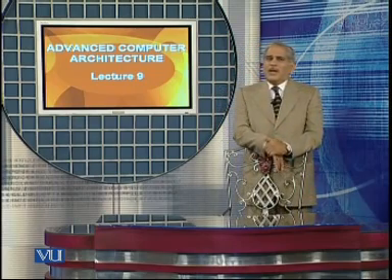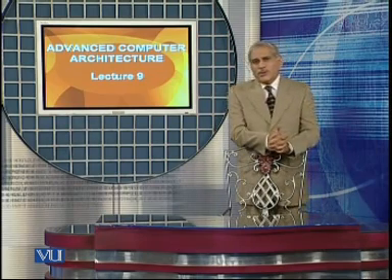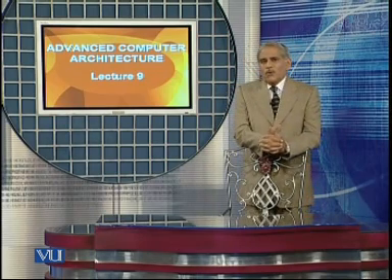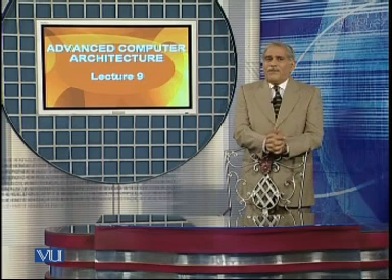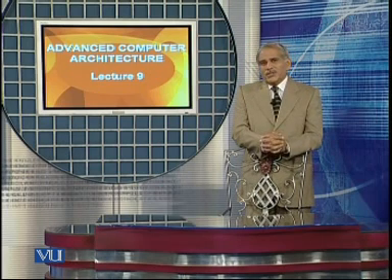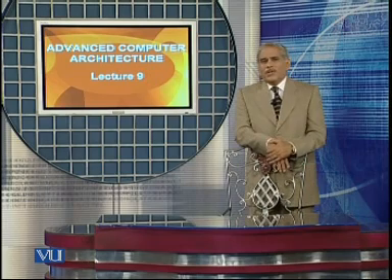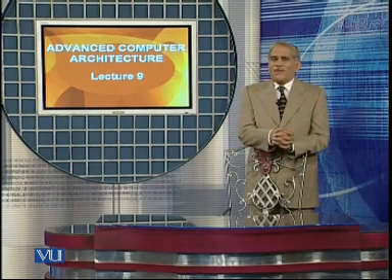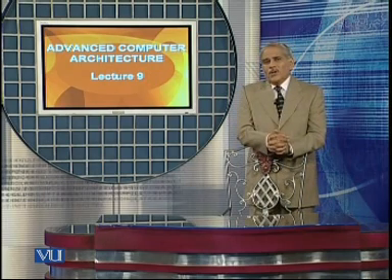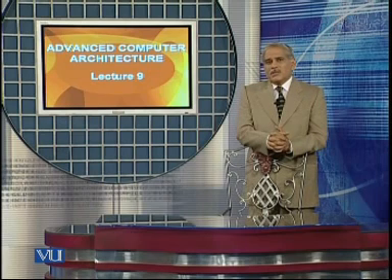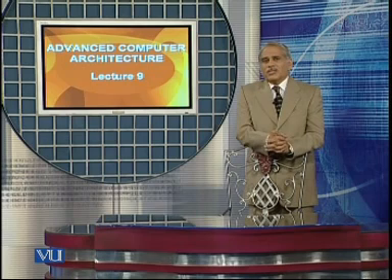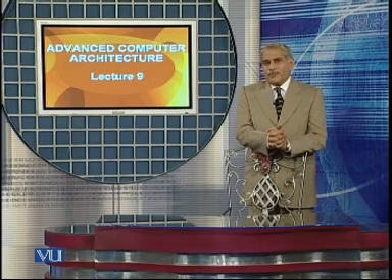So if we use the multi-cycle approach, we can have the cycle length equal to 1 microsecond, which is the longest time required to complete one of the 5 sub-operations required to completely fetch and execute an instruction.